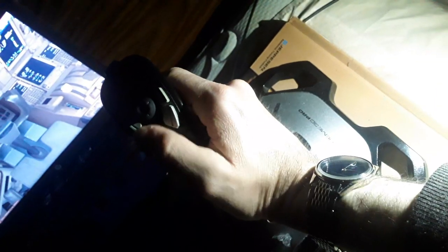And also use the rudder pedals over here. You can see the rudder pedals movement. So this is how you control the side stick. You can leave neutral, you can use the horizontal tail, the stabilizer trim, the thrust levers over here, position. You can actuate the thrust as you desire, and the speed brakes also. So this is the general principle of the flight controls using a side stick like this.